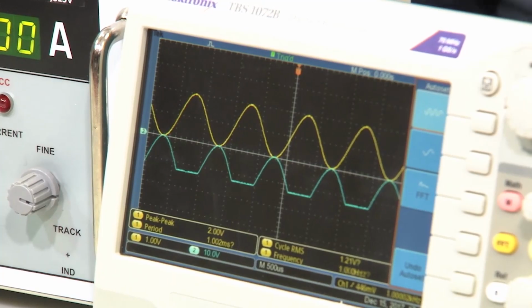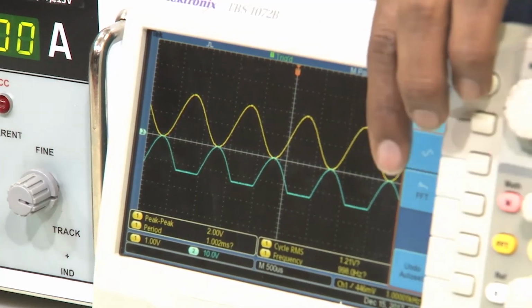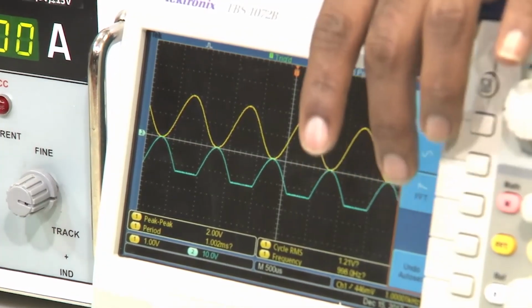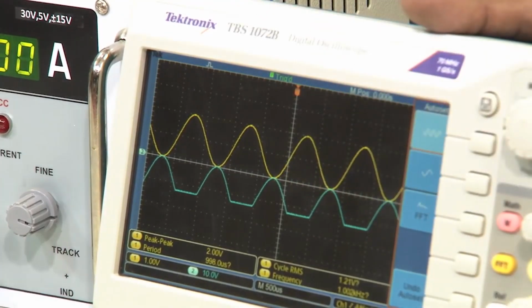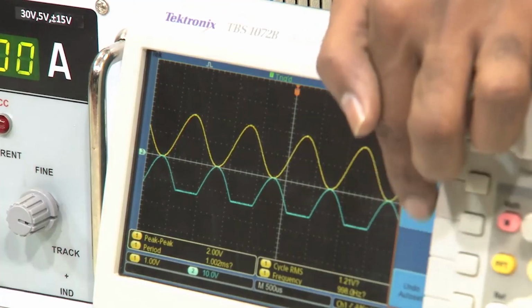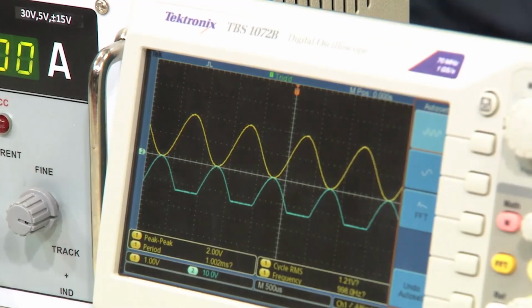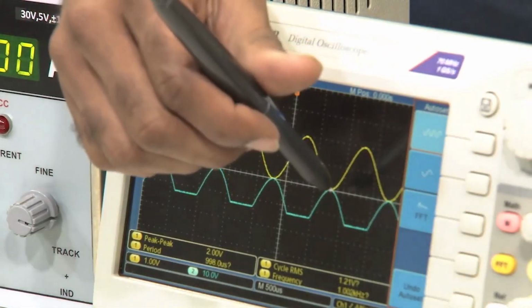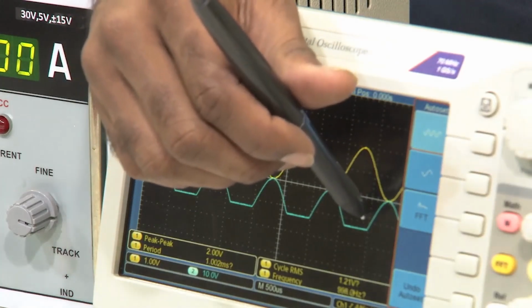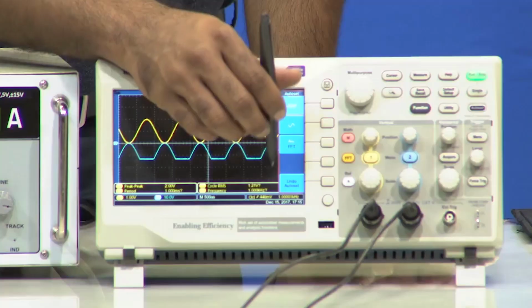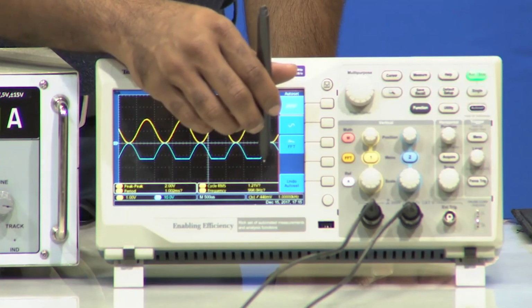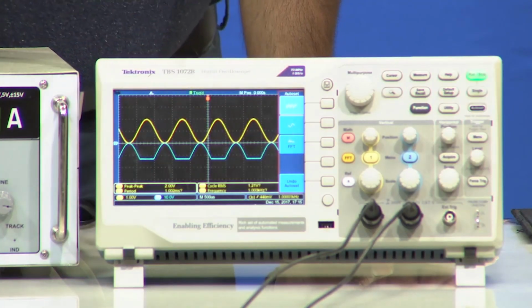input signal. Now, do not go with this, that it does not look like 20 volts, it does not look like 15 volts, right, because we have adjusted the oscilloscope such that even this peak to peak is 15, that is, the blue one is 15. If I put it here, the blue one is 15 and this one, so peak to peak is 20, alright, but this is clipped here, and the yellow one peak to peak is 1 volt.